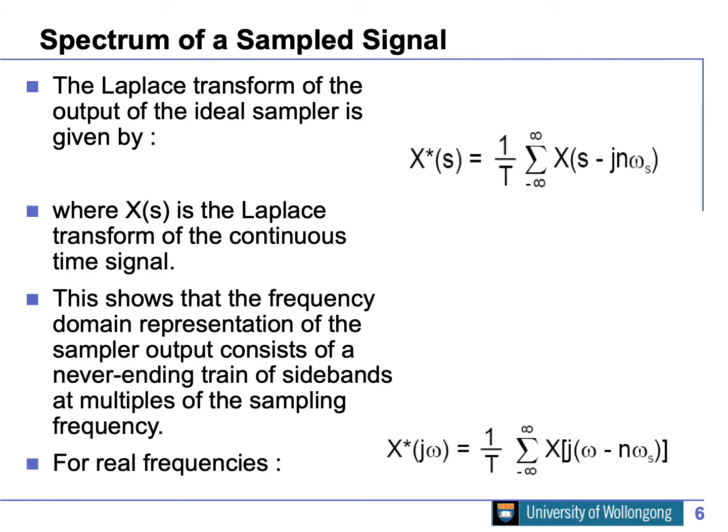To understand why we have to sample at a frequency higher than the Nyquist frequency, we have to look at the Laplace transform of the ideal sampler. If you go back a few slides, you get x*(t), and here we take the Laplace transform. You can see the frequency components in this sequence come from a bunch of different locations, from negative infinity to positive infinity.